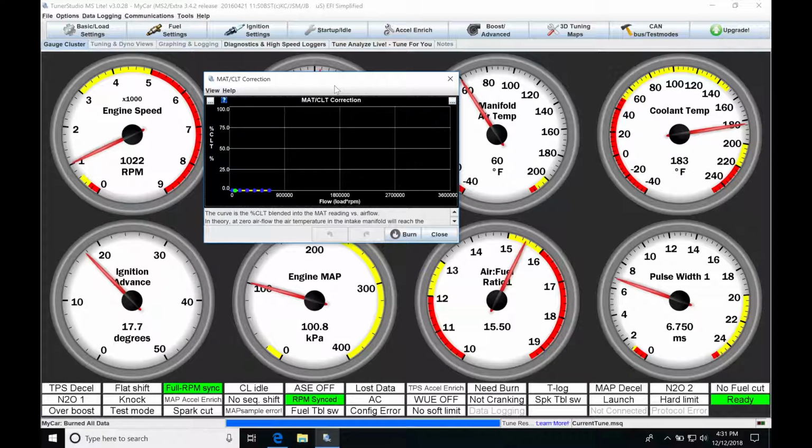And then as you drive it more and more, you're noticing that your coolant temperature remains the same, but you come down to a stop and you let the car heat soak a little bit, maybe for 5 minutes, just sitting and idling. You're going to notice that if you look at your fuel trims, or if you watch your wideband in open loop, your air fuel starts to change a lot. And that's because this air temperature is going to be reported falsely to the ECU, and we're going to have a false air density reading, and then our calculation for that volumetric efficiency for that air mass is going to be incorrectly reported. So that's going to be a major problem.